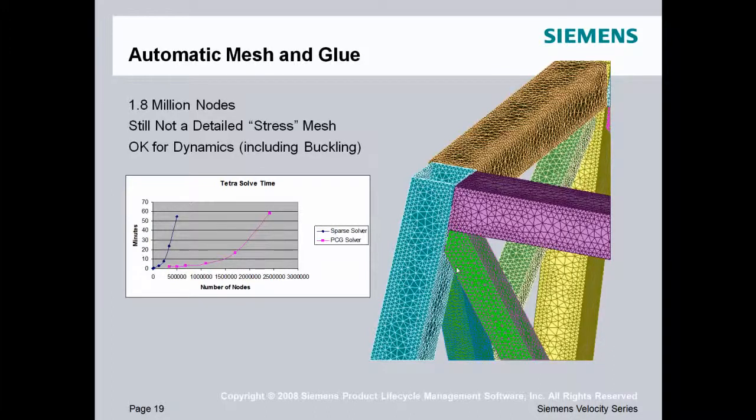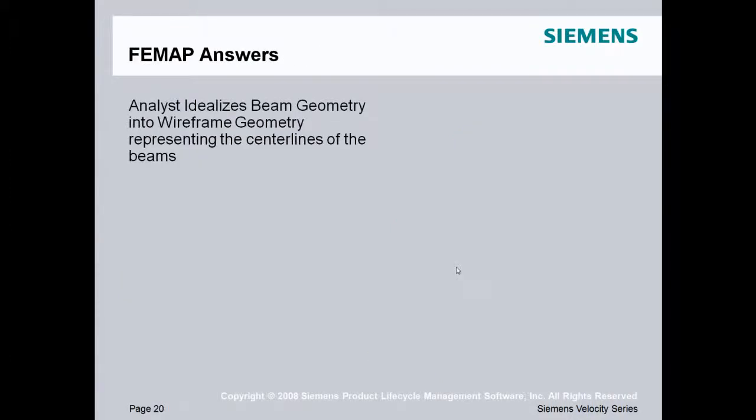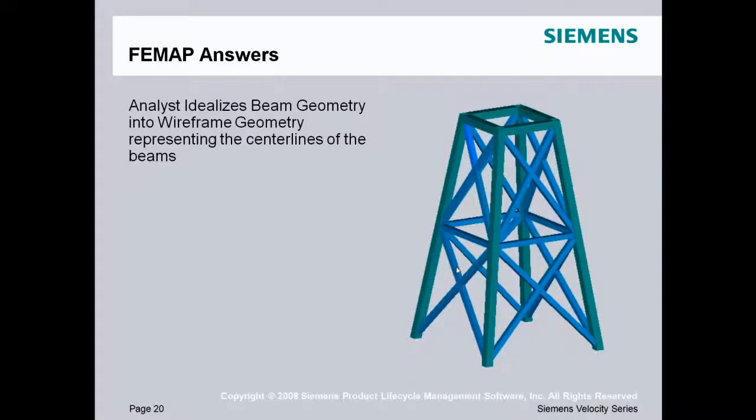However, as you go a little deeper into analysis, like we're going to do today, with a nonlinear buckling, and you get into a transient dynamic solution, the model solve times are going to get to the point where it's basically prohibitive, especially for making changes. So what we're going to do here is basically the standard process a FEMAP user would use.